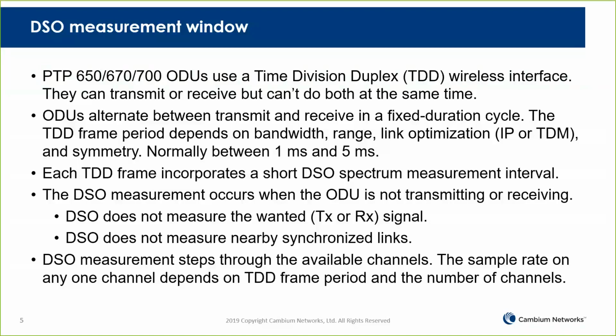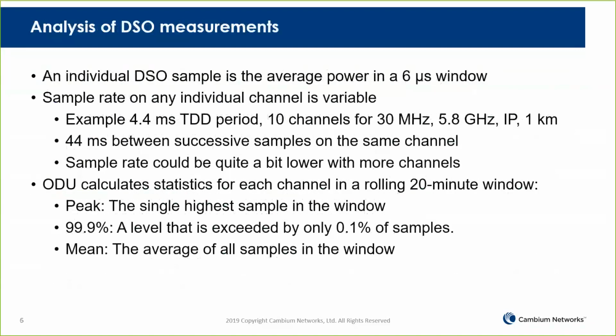That means the time between measurements on a particular channel depends on the frame period, how often we get to make a measurement, and the number of channels, meaning the number of measurements we have to do before we come back to the channel we started on. So the whole DSO feature is based on processing the measurements made in this DSO measurement period.